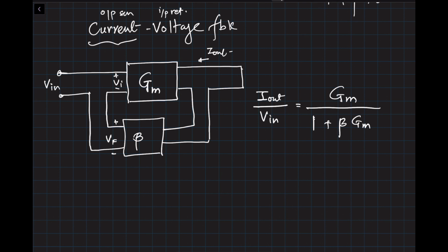So in this case, let's use our intuition that I just taught you a few minutes ago. What is going on at the output? At the output, as it looks like, things are in series. So whenever things are in series, what happens to our output impedance? It should go up. Similarly, at the input, also we see things are in series. There are two series blocks connected, so input impedance will also go up, and that's exactly what happens.